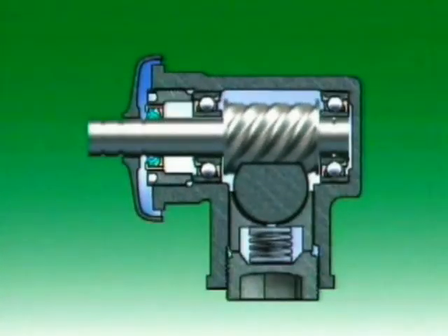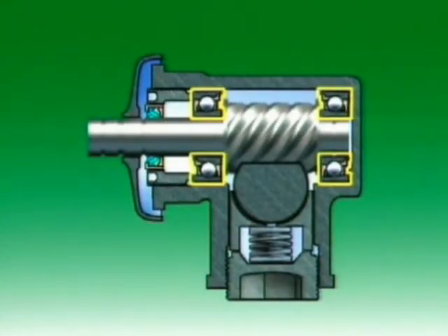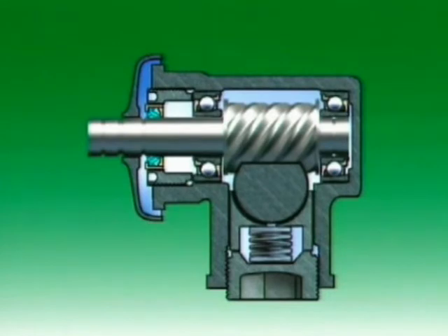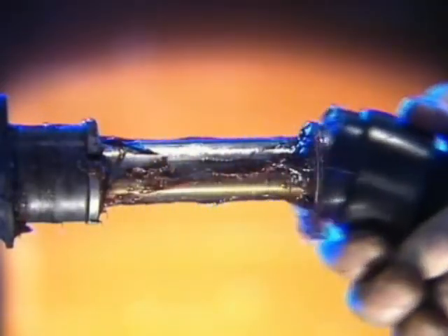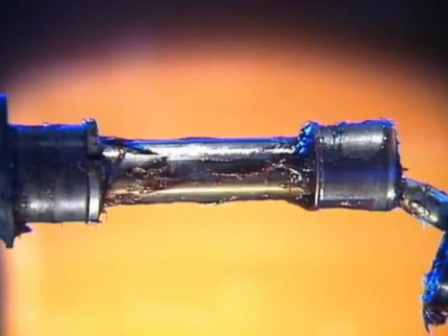The pinion is supported by two bearings in the rack housing. These bearings are preloaded to keep the pinion in the correct position, relative to the rack, and to eliminate free play. The rack and pinion steering box is normally lubricated by grease.